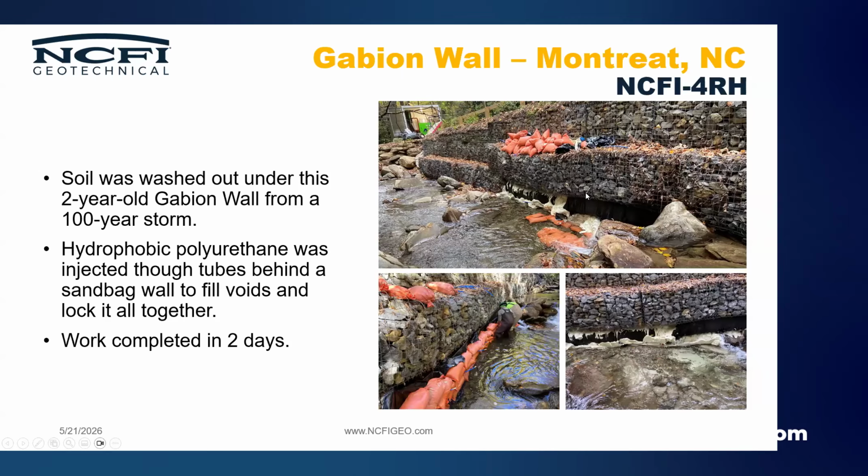The bottom layer of the base for that wall is basically geofabric with riprap wrapped up in it. But there was about an 18-inch gap below that. So in order to form it up and contain the material, again, this was about 18 inches tall and went back 3 feet under the wall. One section was like 27 feet and the other was 30 feet total.